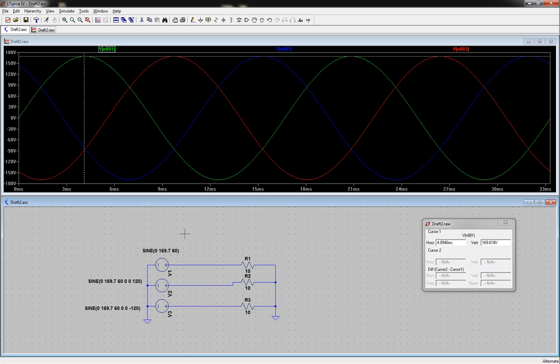Now, like I said, it won't generate the nice looking IEEE standard MOSFET symbol, but what it'll do is generate a little box that has every pin labeled on it. It depends on whether the model labels them gate, drain, source, or just pin 1, 2, 3. Whatever the model has labeled those pins, that's what will show up in the symbol generator. So it'll be just a little box with all the pins and everything, and it's all ready to go, matches the model. So that's kind of a slick feature.